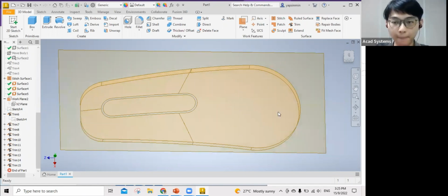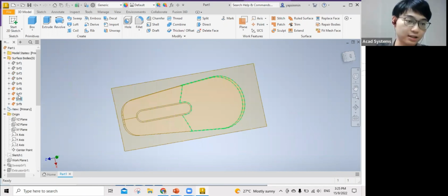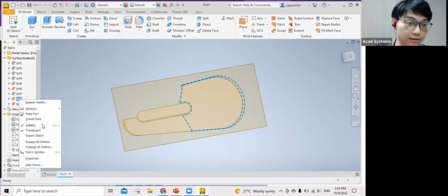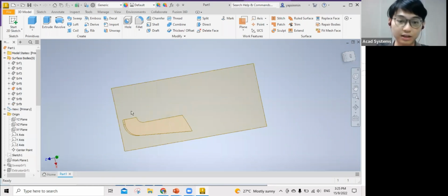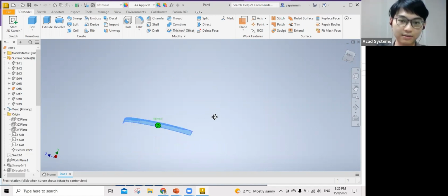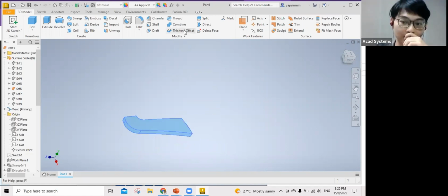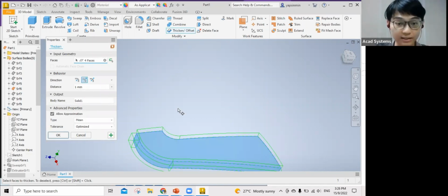Okay, so on the left, you just need to thicken it, and you obtain your mouse. It's a solid model. So you can do it one by one. On this surface, this pen I don't need as well. It's blocking my view. So how to do a thickening? You simply select this surface. Then you are done modifying. So this is the one. The left click, thicken, and then I want it to go outward. Or actually, you can select inward as well.